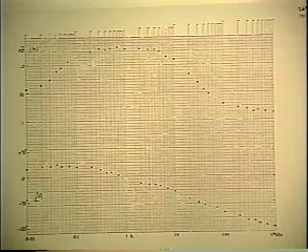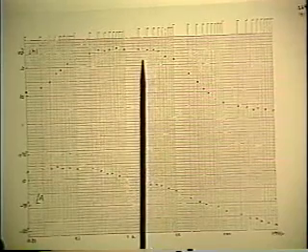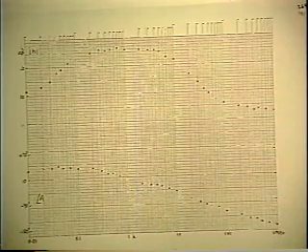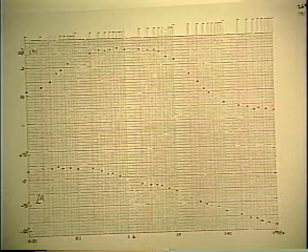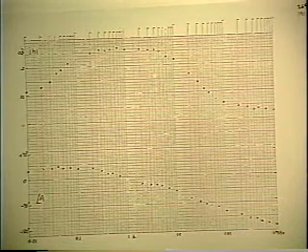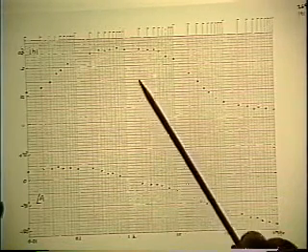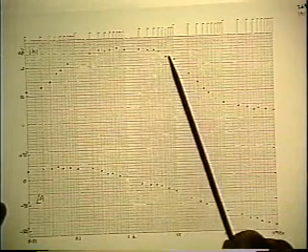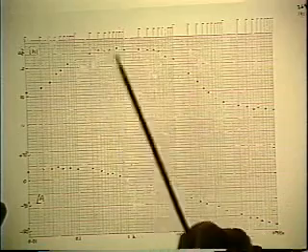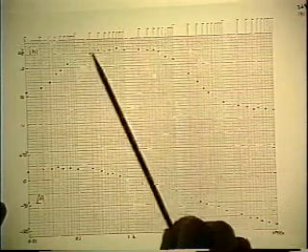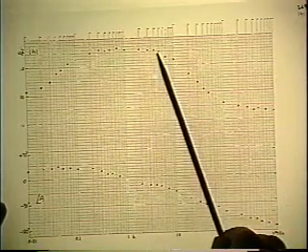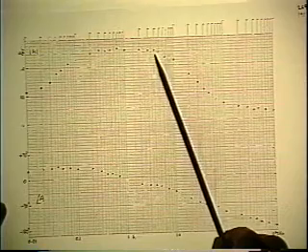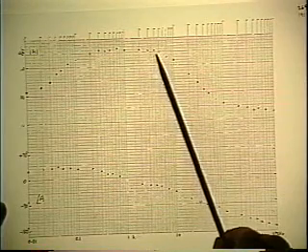So the first thing to do is, in looking at the data, to take asymptotes of the proper slopes and slide them around. In this case, obviously a good starting point is the mid-band flat gain from the magnitude data points. That's the largest gain there is. This is probably the most important salient feature, so it would be good to use that gain as a reference.